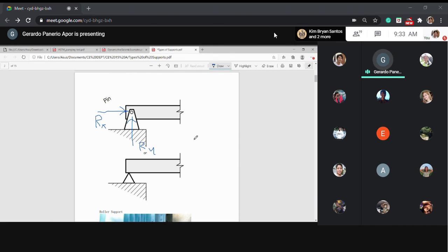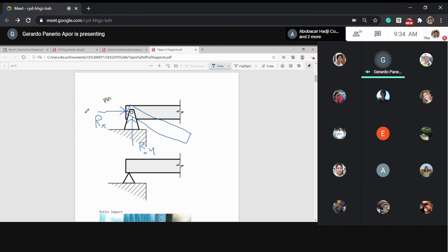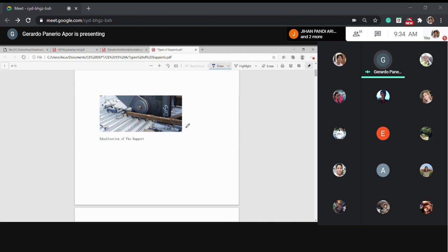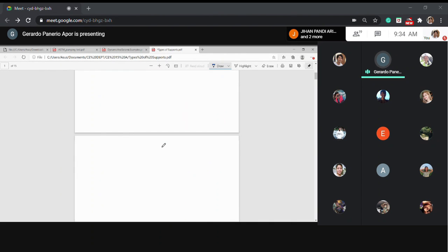Okay, so that is the reaction. Now, this member is continuous. It's free to rotate about this pin, no? So if there is movement down, this structure will just rotate about it. But this structure is intact, meaning it's supported along the y direction and along the rx direction. This is the action of the pin in 2D. Of course, it can support also RZ, but RZ is perpendicular to